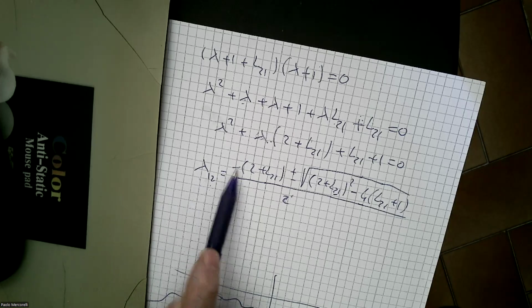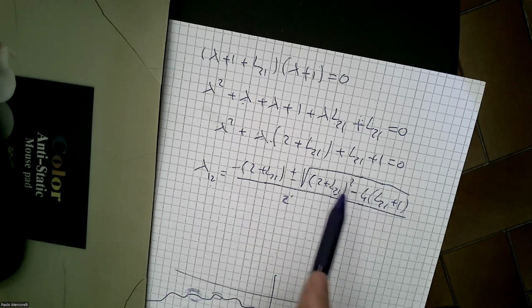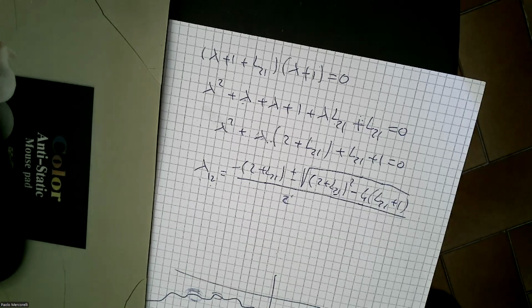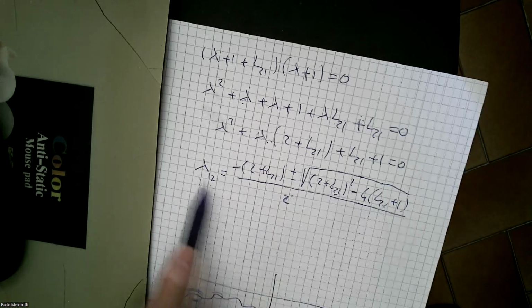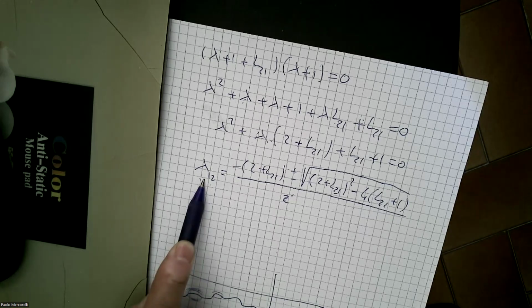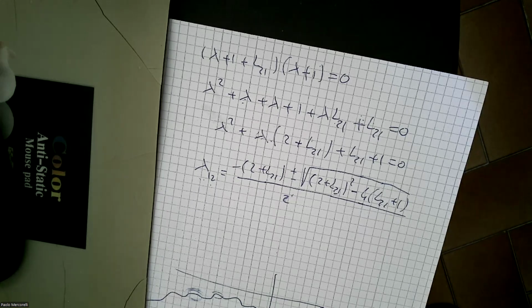It seems to be possible to place two eigenvalues asymptotically stable, meaning with negative real part. Of course, I cannot fix them arbitrarily. Why not? Because we have just one parameter and two lambda. But if the system is detectable, it is possible. This is the idea. We will come back to this next time.